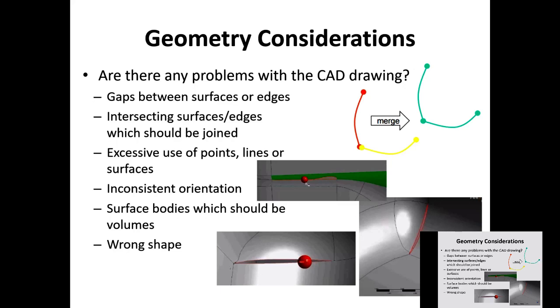So when you see a CAD drawing, you take the shape from the CAD drawing, but you need to create your model, the volume for your CFD model, using the tools in CFD, because you can't have any holes inside your mesh, okay, or voids or unnecessary pointers.